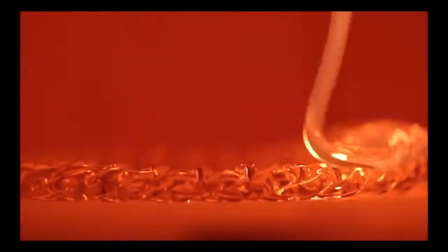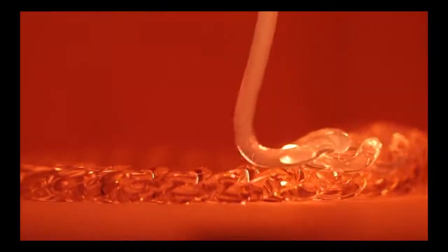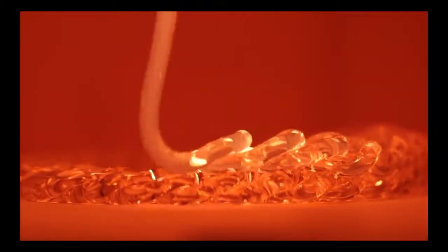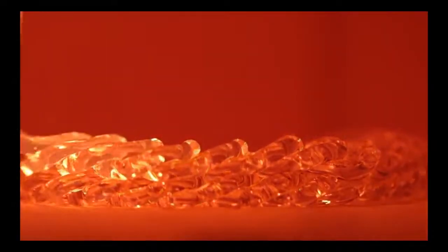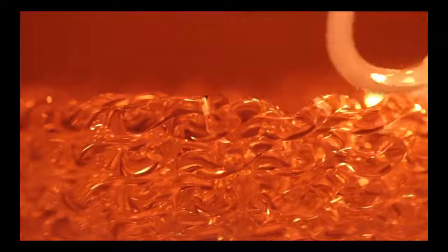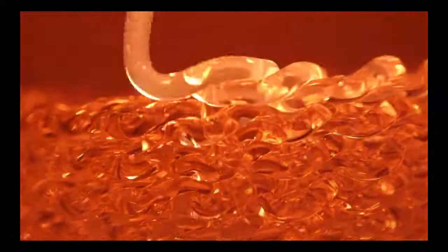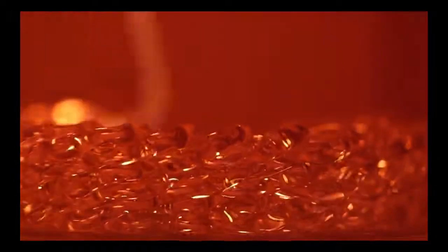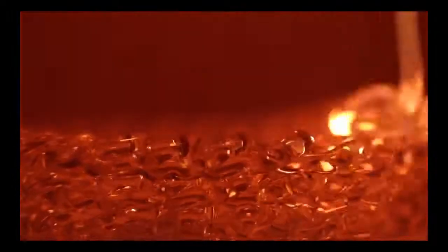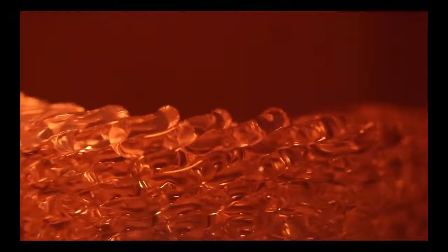This is interesting. When you pour molten glass at an offset, you get these really interesting autocoiling patterns. This is basically the structural instability of the glass. It's what happens when you pour honey on toast. And these patterns could be used to control the geometry that is at the external surface, but also in the internal surface of the product, unlike glass blowing, which only allows you to control the external surface.